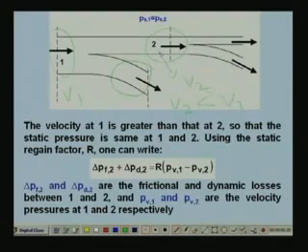So, when you are reducing velocity, what happens? There is a conversion of velocity pressure into static pressure rise. Okay, this I have discussed in the last lecture. This is what is known as static regain factor. Okay, this rise in static pressure due to reduction in velocity pressure is such that it matches with the frictional and dynamic losses in the section from point 1 to 2.